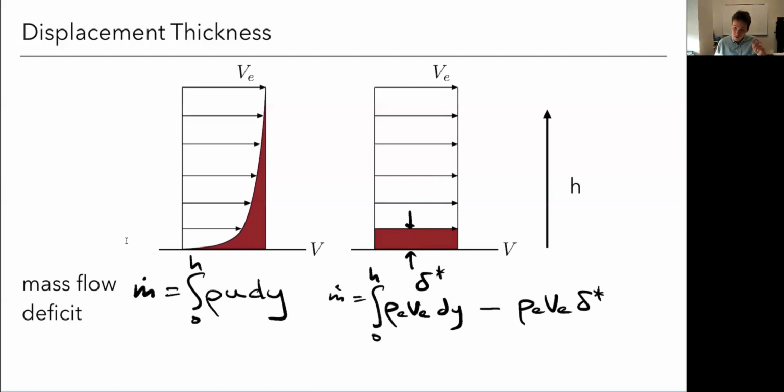And actually the other thing that we do, because h was just this arbitrary height that we defined, right? We just integrate to some point. We don't really know where that is, but we notice that if we go far enough, right, as h becomes larger and larger, this term here, rho u, should approach the denominator, right? By definition, I'm approaching that value. So this approaches 1, so eventually this goes to 0. And so I can go as far as I want, and anything beyond that point will contribute nothing from a point of view of the boundary layer. So by definition, we just take this to infinity because it goes to 0 at some point. So this is the definition of the displacement thickness.